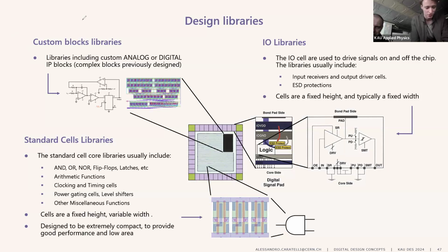I didn't think that circuits can be multi-layer in a physical sense. I thought that all the transistors are just placed one after the other, not stacked vertically. No, actually you need multiple layers. The transistors are one next to another, but you need multiple layers to fabricate the transistor, and then you have multiple layers of routing, one on top of the other, for connecting the blocks together. So the height is in relation to the number of routes?